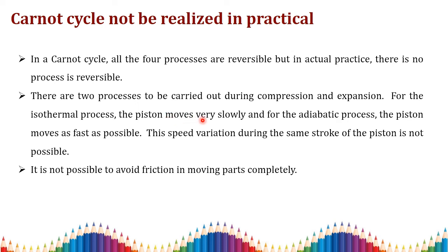During compression the piston will move fast, and during the expansion process it also moves very fast. In the Carnot cycle it is assumed that during compression and expansion the piston moves at the same speed. But in practical cases this is not possible. Also, where moving parts are present, friction will be present, but that friction is considered negligible in the Carnot cycle. So the Carnot cycle is not a practical cycle.